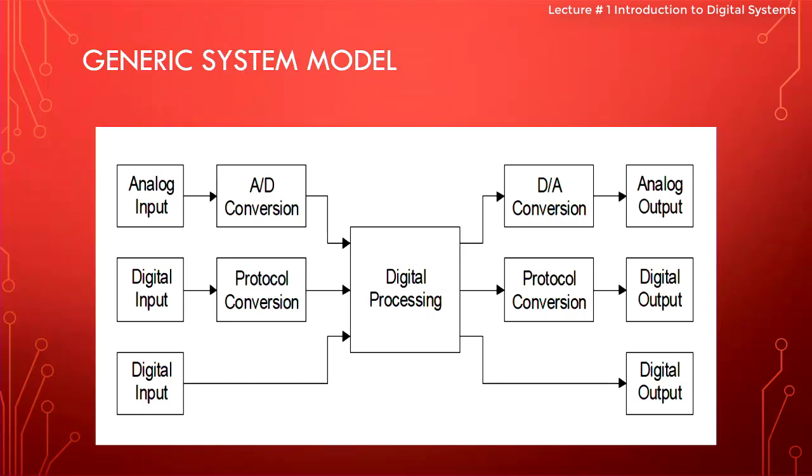Digital inputs are those which are going to generate logic 0 or 1. So you can think of a switch. A switch can either be 0, on or off, right? So when it's off, it's 0 volt. When it's on, it's 5 volt, right? Or can anybody name another digital input? Push button, right? Those kinds, okay?